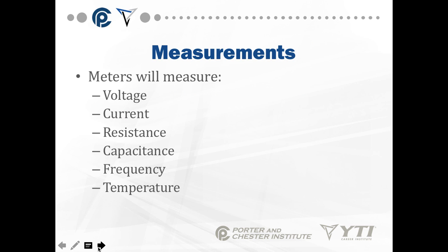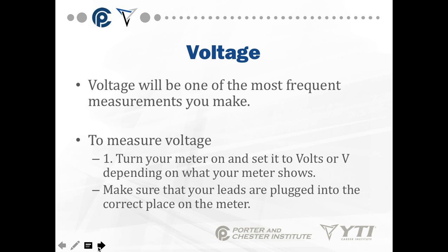Meters will measure voltage, current, resistance, capacitance, frequency, and temperature. Voltage is the most frequent measurement you make. Now, here's the thing. When you are troubleshooting, most of the time you are troubleshooting in a live circuit, so it's extremely important to remember your safety procedures.